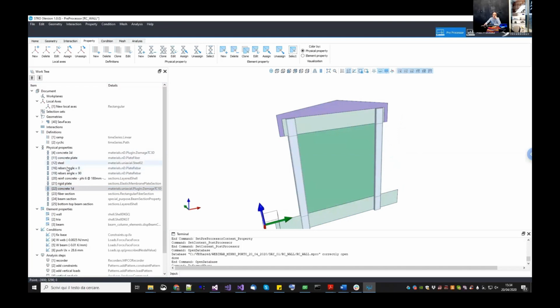So we are going to define a steel uniaxial model. And then in OpenSees, you have something called plate rebar. That basically is a kind of material wrapper that's a uniaxial material for steel. The user gives an orientation angle, and it will convert it to an equivalent plane stress material, acting only on that direction. As it is a plane stress material, it's easy then to use it inside.